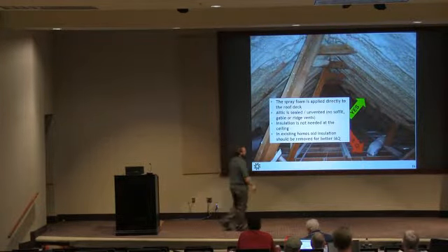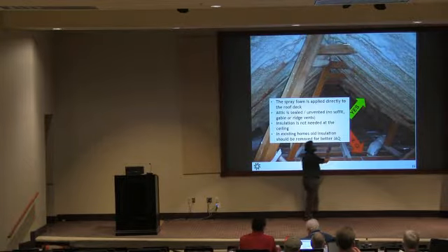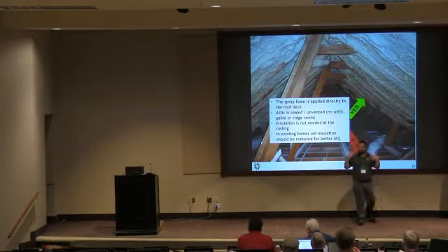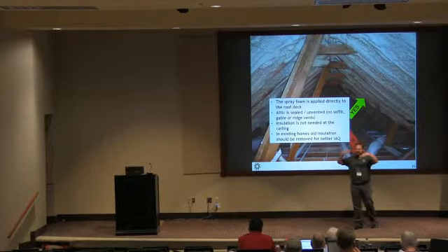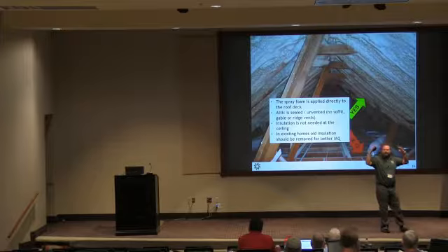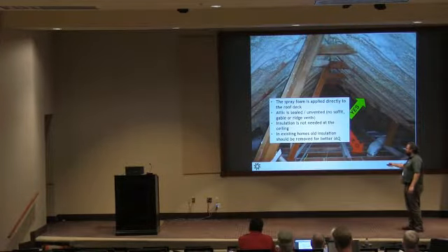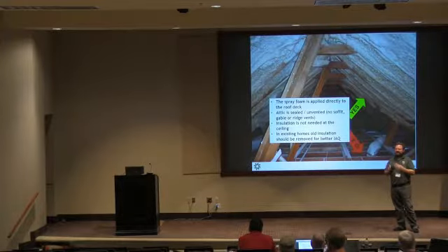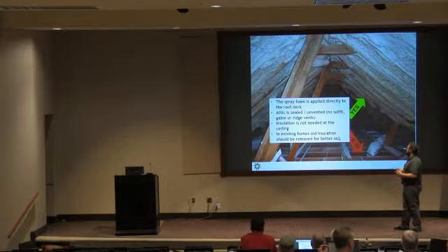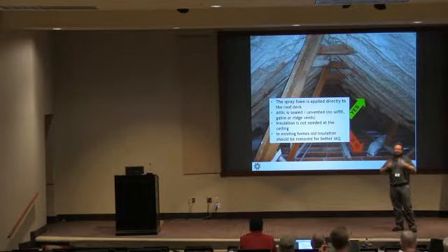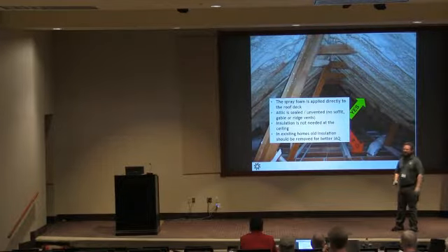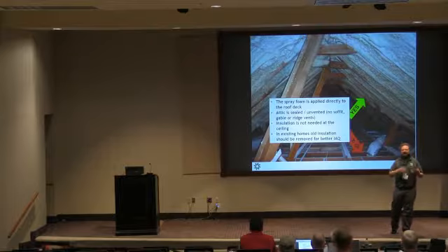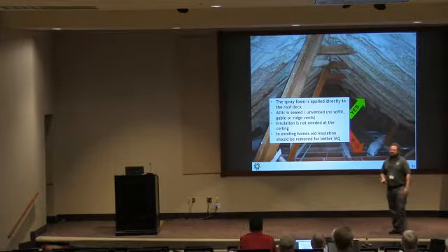And then the other is really indoor air quality. This is a very airtight assembly, and it's now inside your home, right? This attic is now inside the air pressure boundary of the house. So you've brought your attic inside, and if this has been an old vented roof, if there's old fiberglass up there, it's friable. If critters have been getting in there, you've got roach scat, rat scat, and urine. If you're doing this, pay the extra money to have that stuff removed, and it's really for indoor air quality as much as anything else. Because it's no longer your thermal boundary, and it's likely to not yield good indoor air quality if you leave that stuff inside the home.